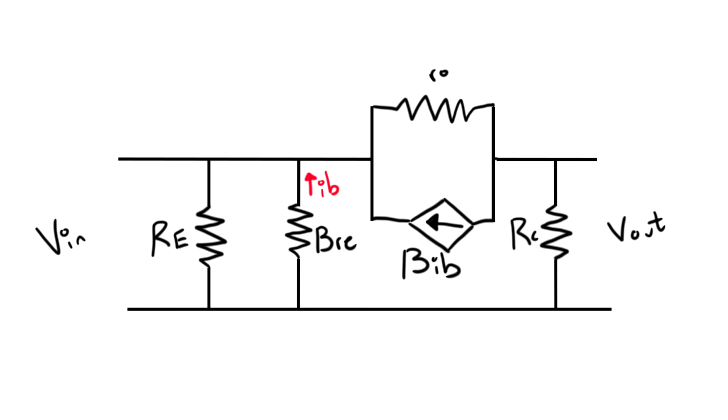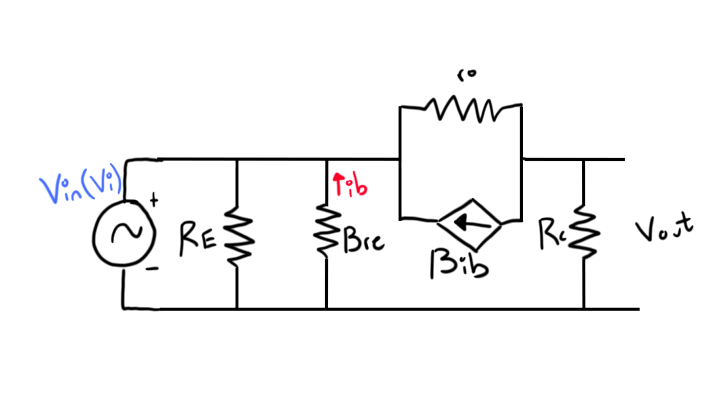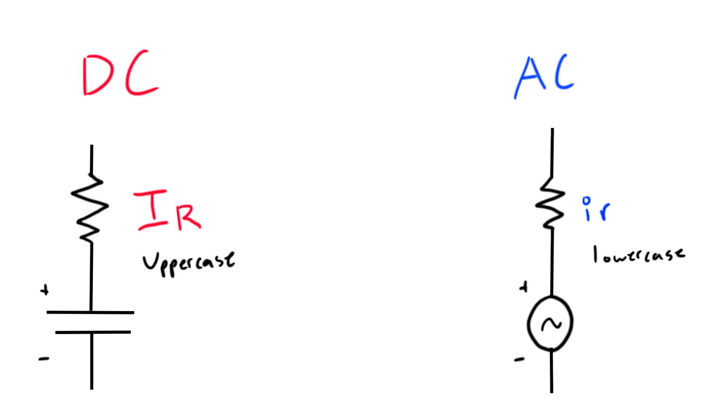For Z in and AV gain, we're going to have to add in an imaginary AC voltage source. Let's call it VI. Now let's show all the currents that are being caused by VI. Remember, we don't have any values for these currents or for the VI. These are new AC terms. Do not get the DC values confused or put them into these calculations. To help make this distinction, try to keep all your currents in lowercase I during the AC phase.